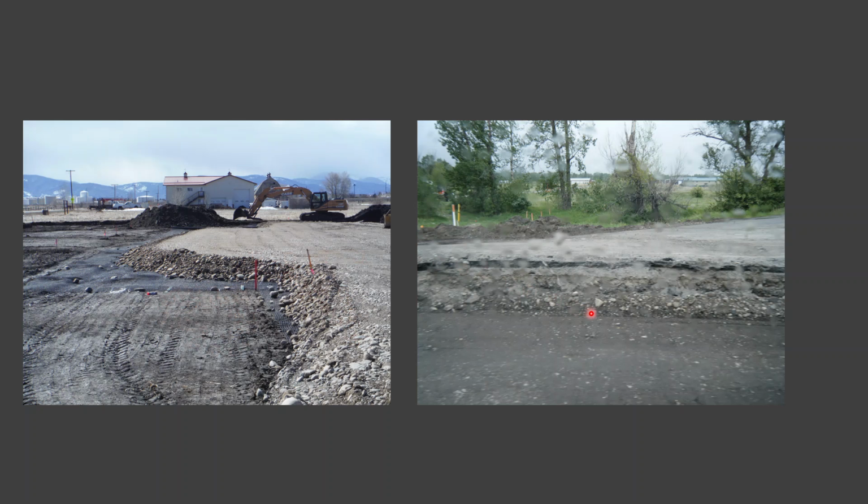It's a little easier to see here on this road section. This is Highway 191 in Montana, and it was excavated all the way down to the compacted subgrade. And you can see these different layers. There are definitely 3, possibly even 4 layers here, where this looks like some pit run material. There might be some sub-base, maybe 2-inch minus, meaning the largest particle sizes in that layer are 2 inches in diameter, which would fit through a 2-inch sieve.